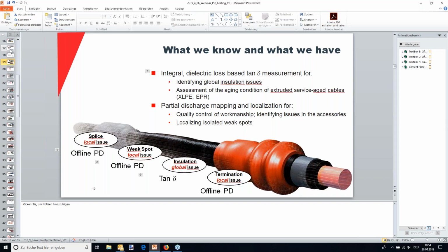You have to be careful with this when you say taking it off of the spool. IEEE knows 3 tests for the VLF test. There is an installation test, there is an acceptance test, and then there is a maintenance test. The installation test is supposed to be done the last time before you touch the cables and joint it or splice it and terminate it. This is to make sure that the mechanical laying did not cause any gross defects. I mean, if you want to, you can do a PD test, but you won't see much.